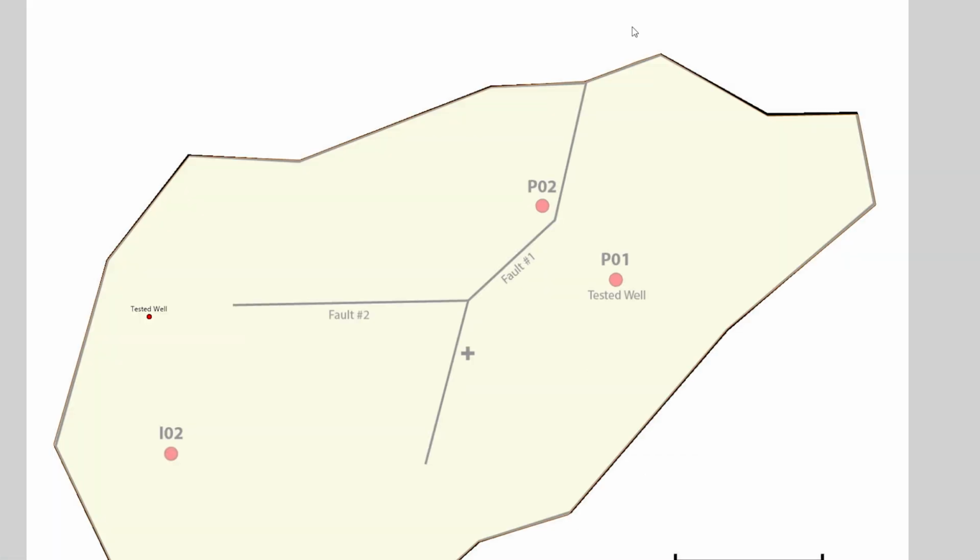The line can be edited by moving the mouse close to the contour and clicking when the cursor changes into a pencil. The nodes are now red squares. Clicking on a red node will delete that point. If the cursor is positioned on the contour, it changes into a cross and a node can be added. An existing node can be moved by click and drag.